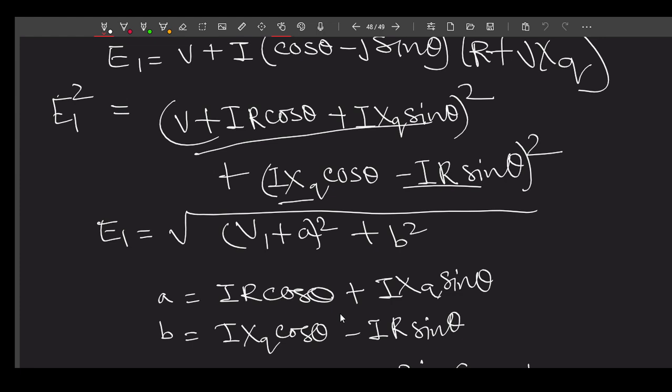Here also, once you connect many machines in parallel, you will lose individual information about the outer terminal voltage. Whatever you get is the combined voltage across the parallel connection. One voltage will appear across all the machines. So basically Vt will become useless. In that case, knowing E gives you some sort of advantage, like how much V you could expect if it was operating in standalone condition.